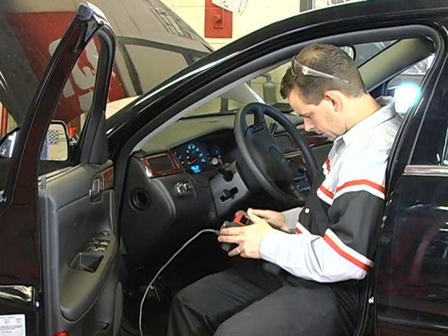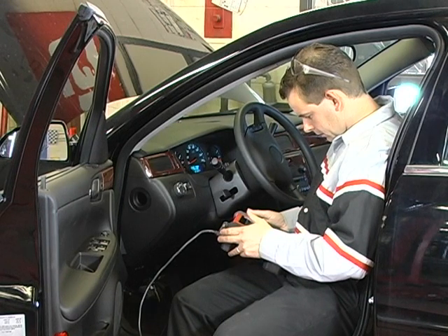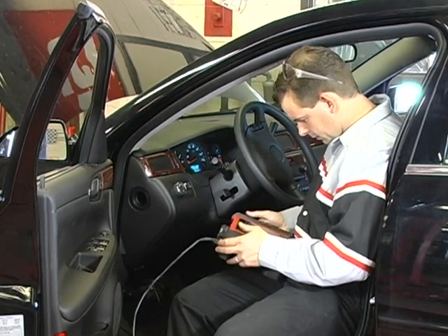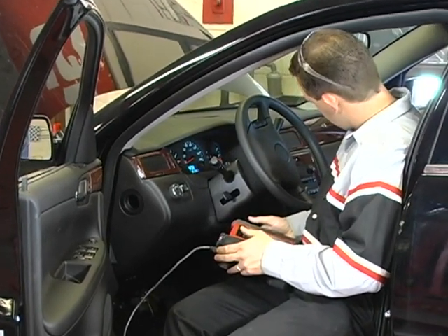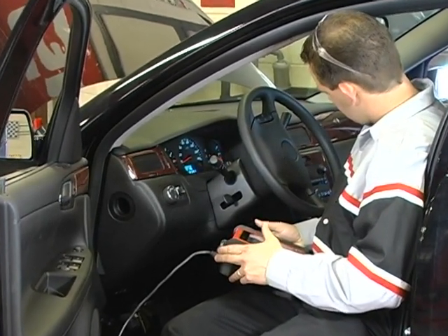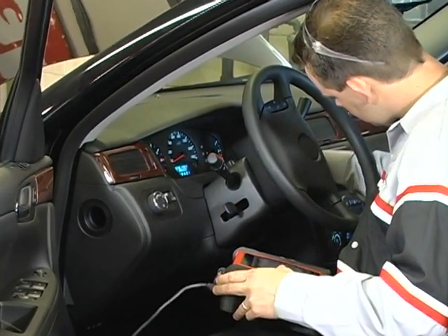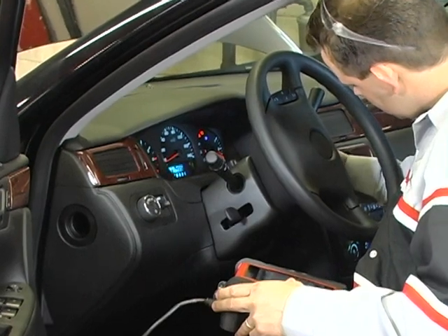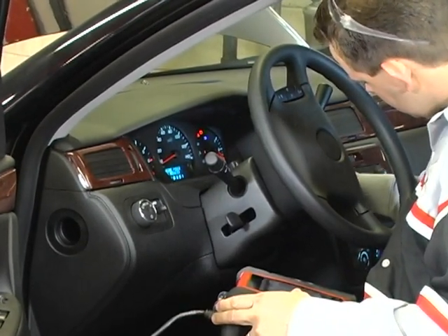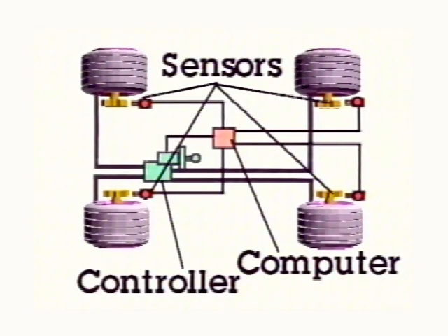To diagnose computer-controlled anti-lock brake systems, you must use a scanner or dedicated tester like this one. It plugs into battery power and into the computer system diagnostic connector. When powered up, this vehicle-specific tester will show the system troubles quickly and efficiently. When using tester instructions, you can troubleshoot wheel speed sensor circuits, solenoids, servo motors, and other electronic components in the ABS system.